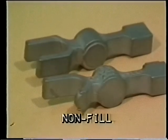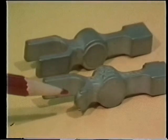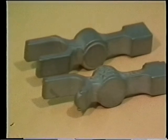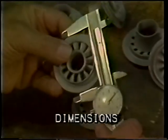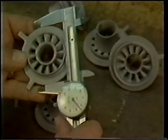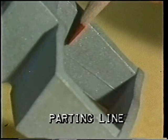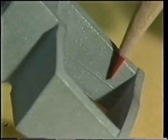Non-fill, often called a misrun, is a condition in which the casting shape is not completely filled out by the molten metal. Generally, this occurs on thin sections where the metal solidifies too quickly. Dimensional discrepancies can result with insufficient tolerances or improperly applied shrinkage allowances. A parting line is a plane on a pattern or a line on a casting corresponding to the separation between the top and bottom portions of casting tooling.